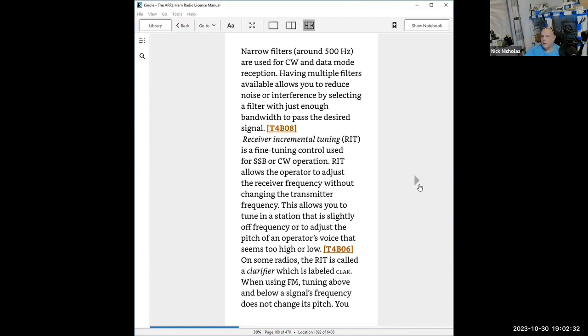So that protects you. But if you're transmitting on 440 megahertz and it's getting into your wife's baby monitor, and let's go with something simple, that baby monitor is down at 50 megahertz, then you don't want the high frequencies to get into that baby monitor. So if you put a low pass filter on it set for, say, 60 megahertz to pass everything below 60, that baby monitor will be fine. I'm not saying that baby monitors are on those frequencies, but I'm just giving you an example if it were. Okay.